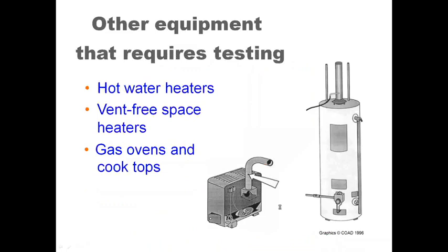Too many contractors go down there, especially HVAC contractors. They buy a combustion analyzer, and they forget there's other appliances that might need tested. The furnace is typically connected to the hot water tank. You need to test the hot water tank too. You should test the stove. You could test the dryer.